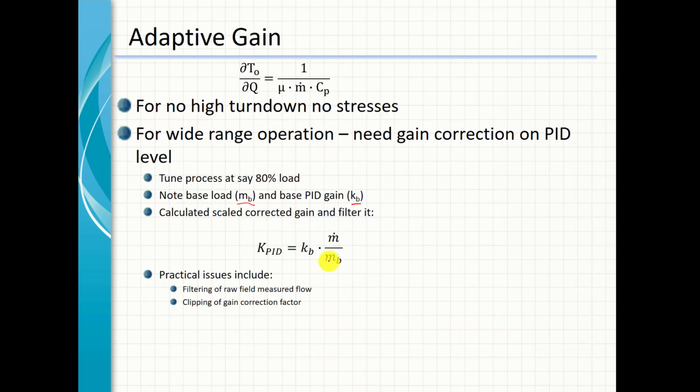So it takes your two reference constants, which is your reference gain and your reference flow rate, and multiplies it by this ratio here. So if we add 10% throughput, you're going to have 10, and let's say that's 80%. That's 80% of design, so it's going to be 1/8. You can see on the previous graph, it would have reduced the gain significantly to cater on the feedback loop for the high process gain.